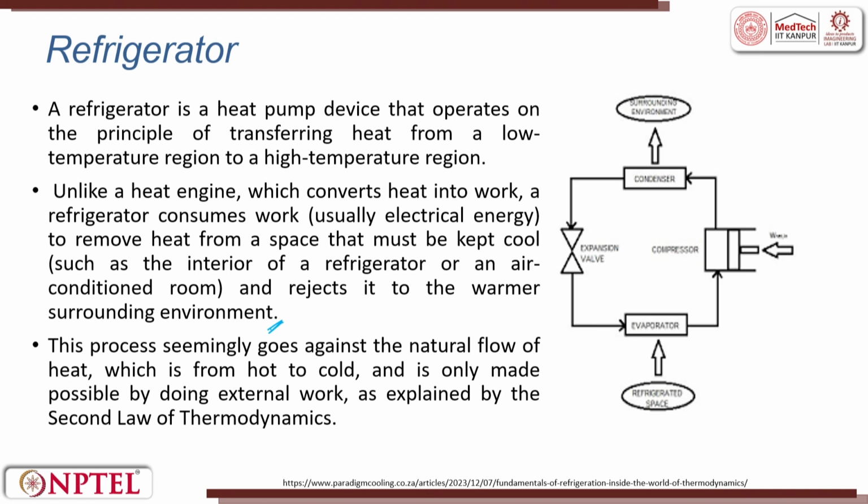So, this is the expansion valve. We have seen this in the previous lecture itself. You have a compressor where pressure and temperature increase, then you have a condenser, then the expansion valve, then the evaporator. From the evaporator it goes to the compressor. Once the vapor is compressed, it then expands, because it has to take in heat and give the cold air.